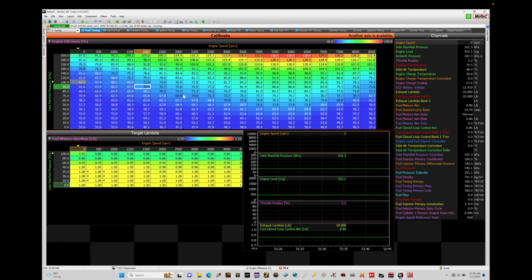If that fails for any reason, might be a wiring problem, it becomes unplugged, maybe the sensor goes bad, and we're in racing conditions, we want to have a way that we can call on a value that can be an estimated value that's very close to the actual reading of our inlet manifold pressure sensor, so that we can still continue to calculate things like our engine load and deliver the proper fueling and spark timing to the engine, so we can at least get the engine off track safely and not go into a dangerous condition or where the engine just completely shuts off. So we want to use the estimate table as a fail-safe backup to our map pressure sensor.